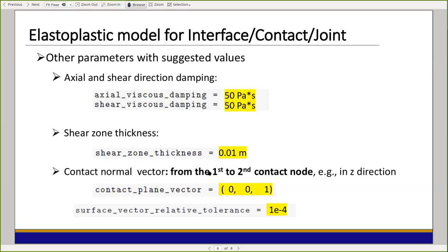Just a note: there's a big note in the lecture notes and in the DSL. If you flip nodes 1 and 2, you're really modeling Velcro. Instead of contact, you're really modeling a pull-out, which has some tension. So you can actually model Velcro as well, if you want, but you need to know this. As an engineer, as an analyst, you need to know that you can do that and when you want to do that.